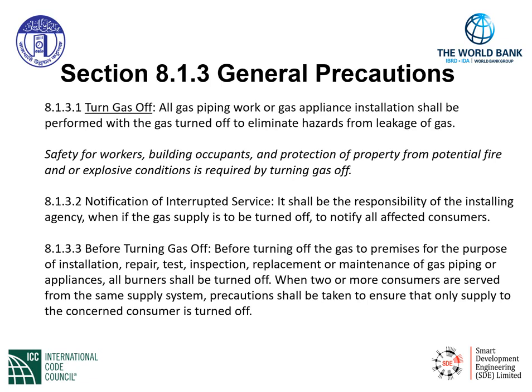Section 8.1.3.2, Notification of Interrupted Service. In this particular section, it's the responsibility of the installing agency, if the gas supply is to be turned off, to notify all affected customers. This is a notification statement here, of course, to notify the end users.